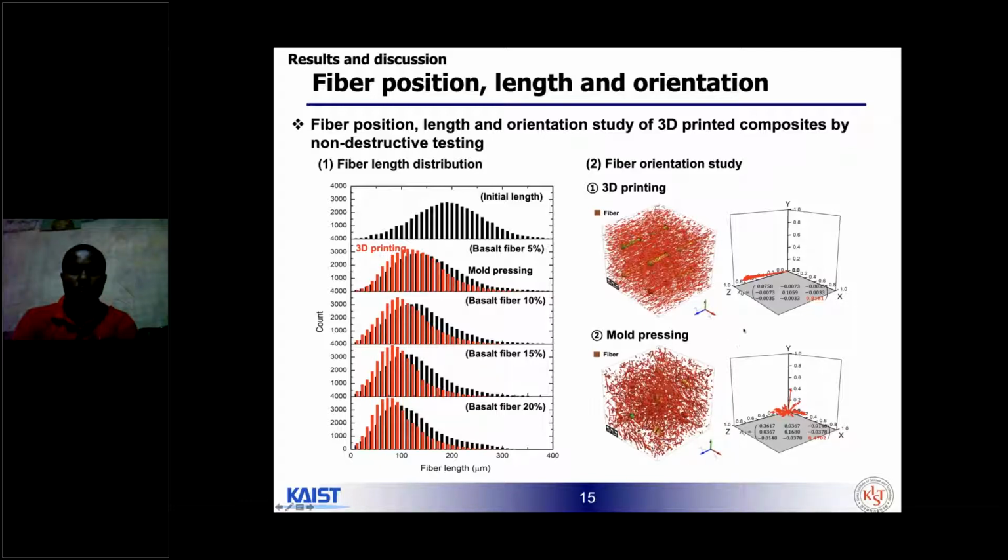Surprisingly, the narrow nozzle of 3D printing induced markedly high fiber orientation, with an A33 value equal to 0.8. This provides a high degree of anisotropy to the material.